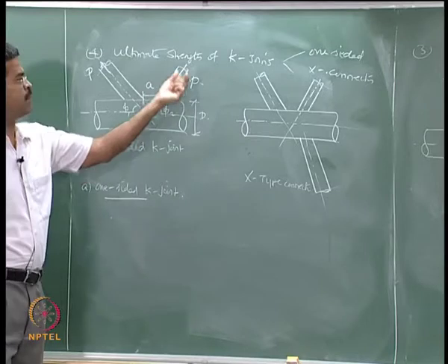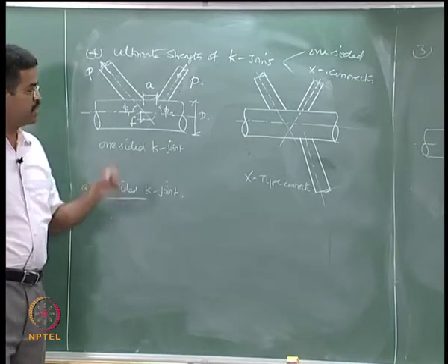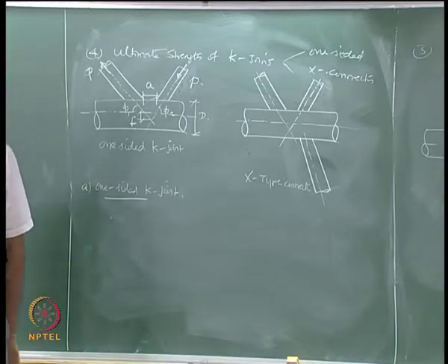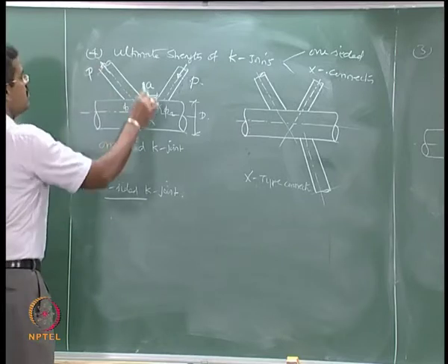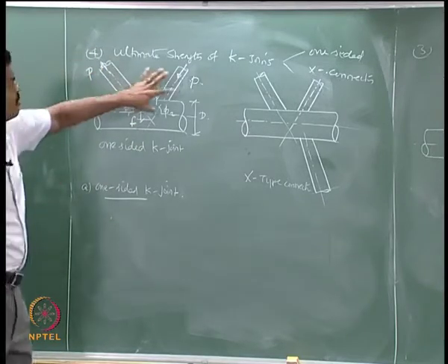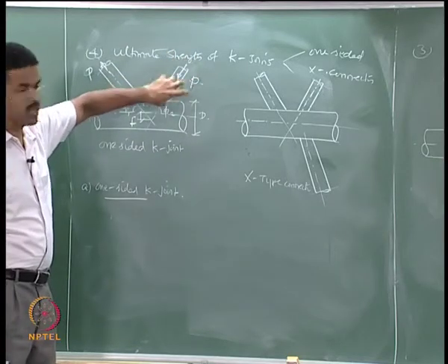When the compressive force is applied to the brace, then it actually governs the design strength compared to the strength in tension. So we will not consider the brace subjected to tensile forces, we will talk about the brace subjected to compressive force.